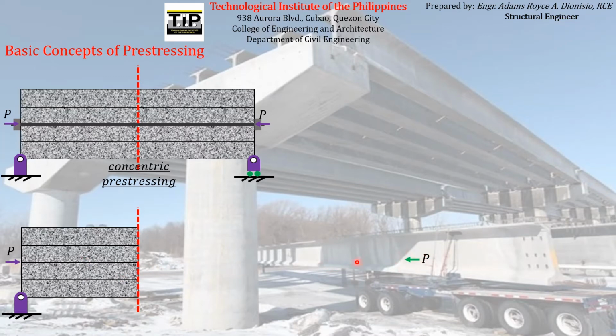And that compressive force actually produces what we call axial stresses. And we usually assume that those axial stresses act as uniform along the cross-sectional area if the force is acting along the centroid of the cross-section, which is the case here. That's why we can call this an axial force, because it acts along the centroid of the cross-sectional area. And if that is the case, the stress that this axial force produces is assumed to be uniform all throughout